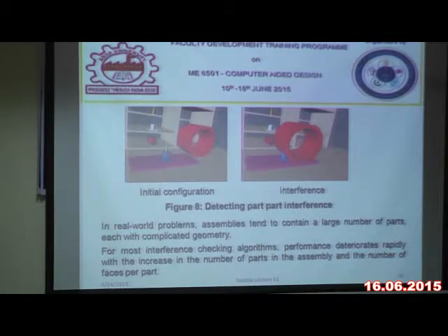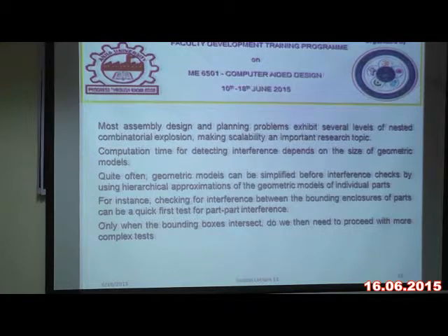Real world assemblies tend to contain a large number of parts, each with complicated geometries. For most interference checking algorithms, performance degrades rapidly with the increasing number of parts in the assembly and number of faces per part. Most assembly design planning problems exhibit several levels of nested combinatorial explosion, making scalability an important research topic.